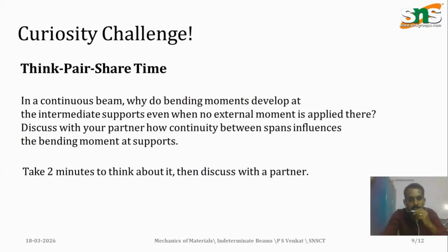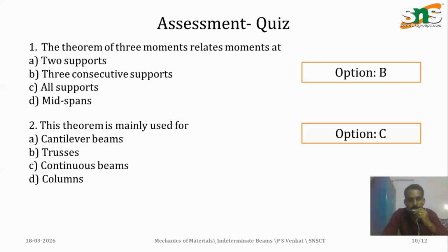Next, we move to the curiosity challenge. Now, let's think critically. Why do bending moments develop at indeterminate supports, even when no external moment is applied there? Hint: it is due to continuity of the beam, load transfer between spans, and restriction of rotation. Pause and discuss with your friends for answers.